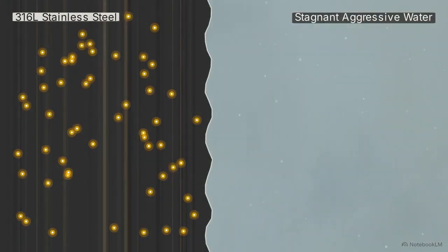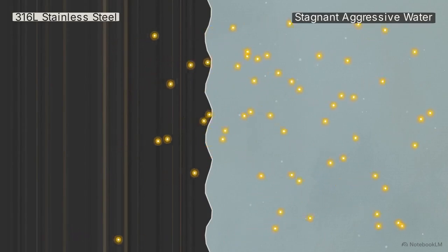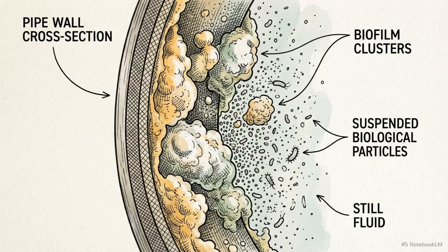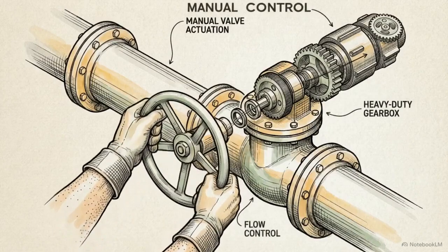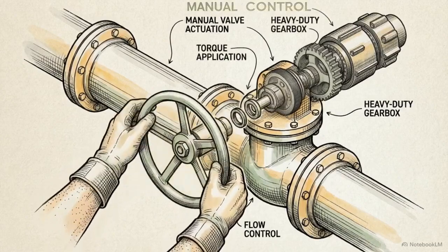That stagnant water acts as a catalyst. It promotes ion leaching from the stainless steel and allows microbial byproducts to accumulate, both of which increase the local conductivity rating. Mastering conductivity requires controlling the physical geometry and flow rates of the piping as effectively as the filtration units themselves.